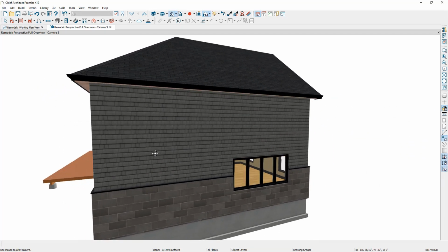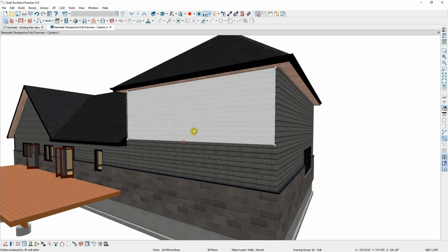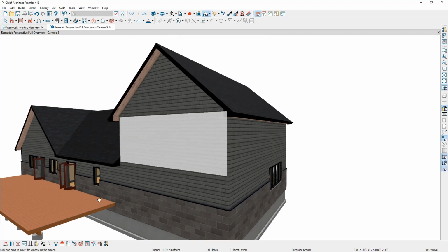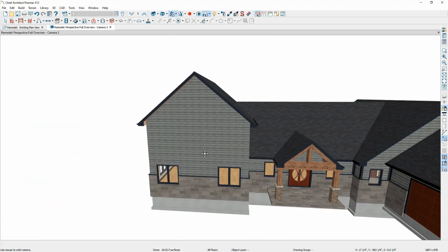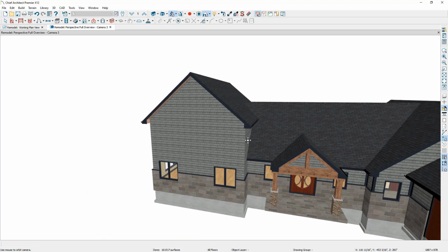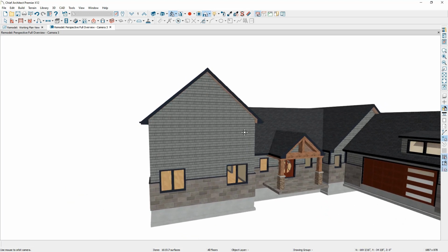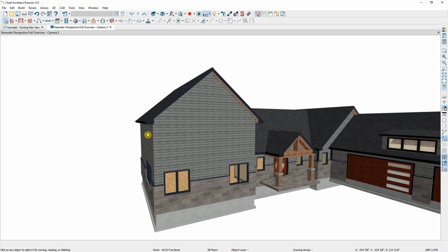If we swing around our view to the back side and select this roof, there's a tool down here for gable wall, just a little shortcut to quickly create the gable walls. Additionally, if you wanted to change how the pitch builds over individual walls, such as this wall on the right and this wall on the left, we can select these walls.